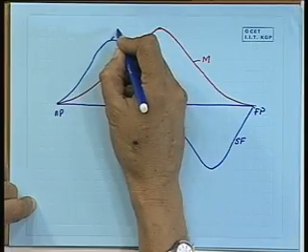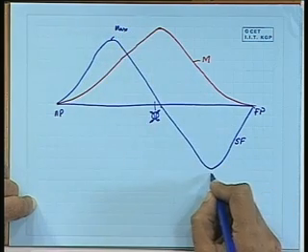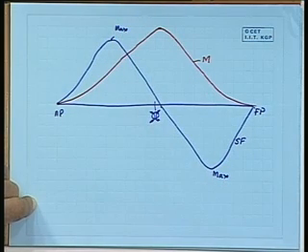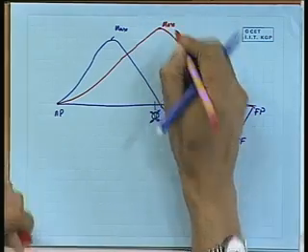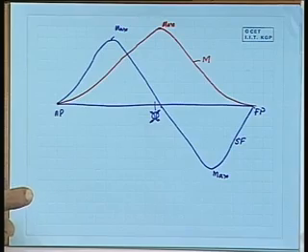So, when it flexes, basically there will be some nodes one can perceive which will be away from the two ends, and somewhere there the 0 displacements will be there. That we will try to say in more detail when we do something about ship vibration. Okay. So, here we have a maximum value of SF, here we have another maximum value. Out of the two, one will be absolute maximum, and somewhere here we have the maximum value for the bending moment. Now, what are we going to do with these maximum values?